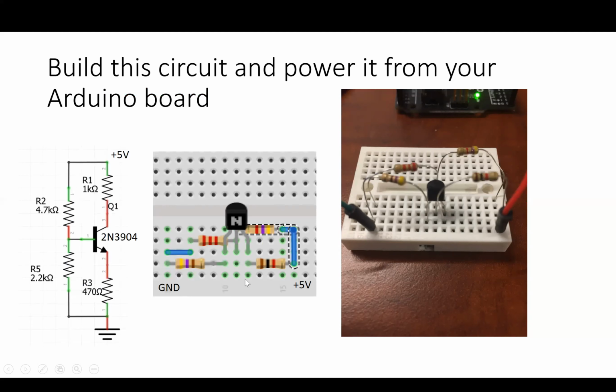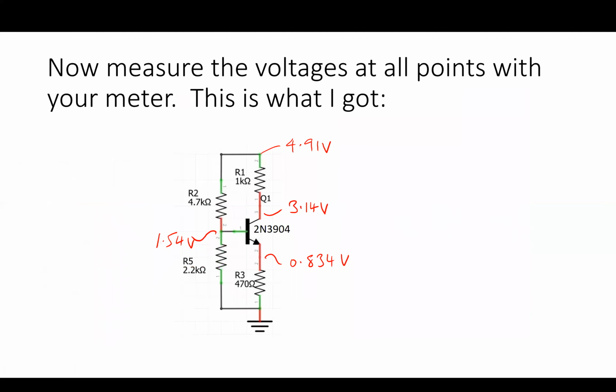So go ahead and make this circuit. Here is the Fritzing pretty layout, and here is the real layout on my kitchen tabletop. And these two leads then are just the plus 5 and ground connections on my Arduino board. Even although this is a very simple circuit, please go ahead and put your ohm meter between here and here and make sure there isn't a short, because you don't want to have to be running out buying a new Arduino in the middle of this course.